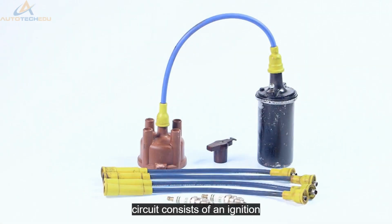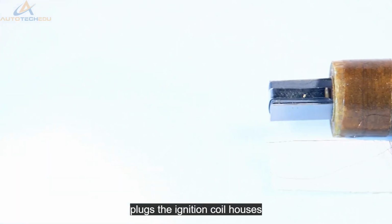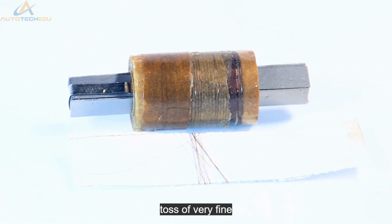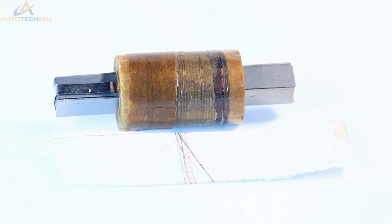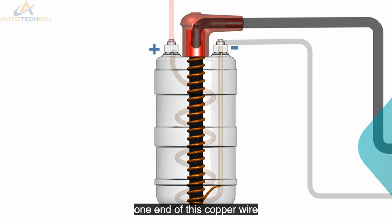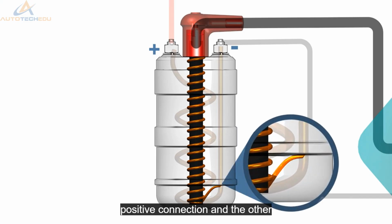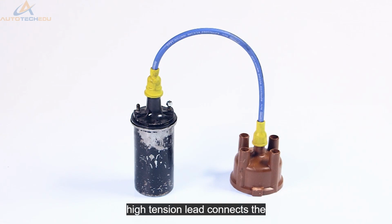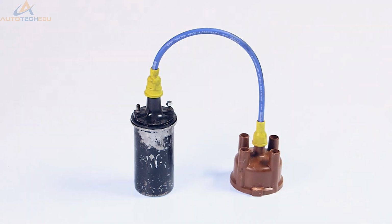The secondary circuit consists of an ignition coil, high tension leads, distributor cap, rotor, and spark plugs. The ignition coil houses another winding with about 20,000 turns of very fine enamel-coated copper wire. One end of this copper wire is connected to the primary positive connection, and the other end connects to the high voltage output terminal. A high tension lead connects the coil to a distributor cap.